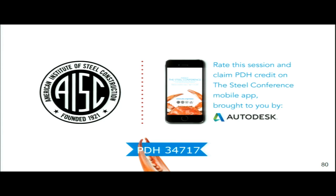Right. So can we consider some certain stiffness in the glass supported floor? When I do a computer analysis, usually you just model the columns and the beams. Can I model the glass in the slabs? The question is, you mean you talk about the cladding of the building? Yeah, that has to be modeled. Clearly that has to be in there. Clearly, the cladding has to be part of the model, as well as any concrete walls in the building.